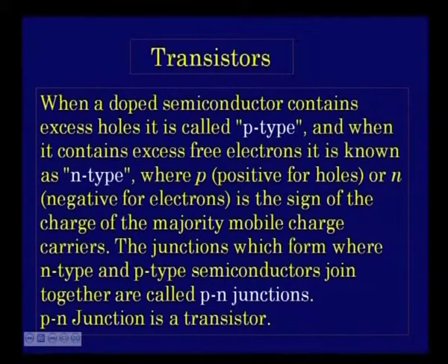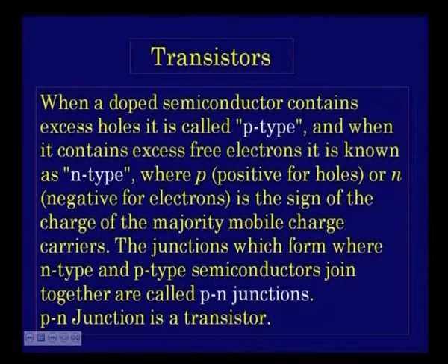Now, if you are replacing silicon by a trivalent system like aluminum, silicon is having 4 electrons. Now, you are removing one silicon atom and you are putting in a 3-valent system like aluminum. So, that means the number of electrons that you are introducing is lesser, or you are introducing a hole. A hole means a positively charged thing. It is not a positively charged particle, but in principle it is a positively charged thing.